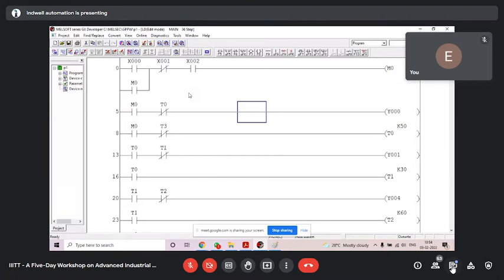In your college project, you will have an issue of funds, because you are going to invest there, so you can ignore the start stop push buttons and can start from the HMI. So I shall use X0, X1. Let it be the same program. I hope you remember yesterday's program. The sequence you remember: first the red lamp will be on, then the yellow lamp, then forward direction, then reverse direction. X2 should be always on, and green will be on with the motor.